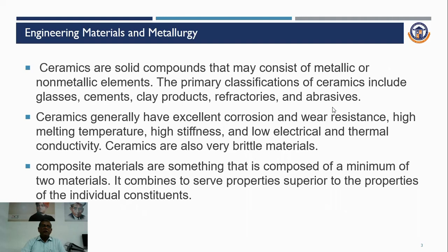Ceramics are solid compounds that may consist of metallic or non-metallic elements. The primary classification of ceramics includes glasses, cements, clay products, refractories, and abrasives. Ceramics generally have excellent corrosion and wear resistance, high melting temperature, high stiffness, and low electrical and thermal conductivity. Ceramics are also very brittle materials.